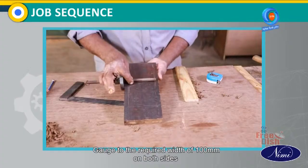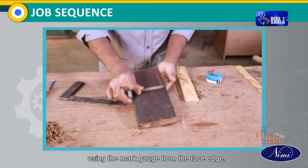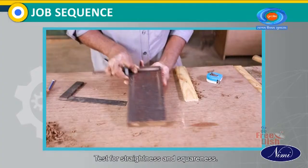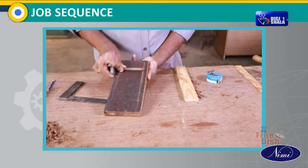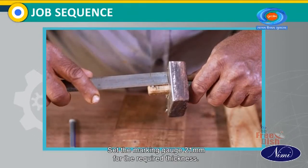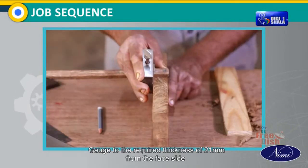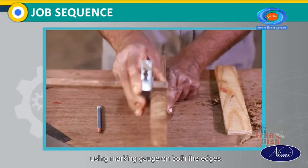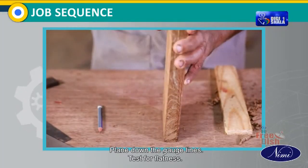Gauge to the required width of 100 millimeters on both sides using the marking gauge from the face edge. Plane down the gauge lines. Test for straightness and squareness. Set the marking gauge to 21 millimeters for the required thickness. Gauge to the required thickness of 21 millimeters from the face side using marking gauge on both the edges. Plane down the gauge lines. Test for flatness.